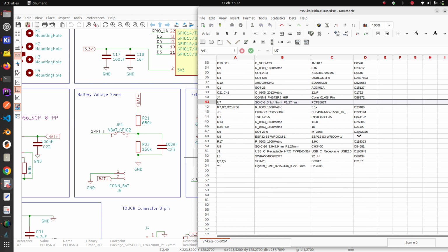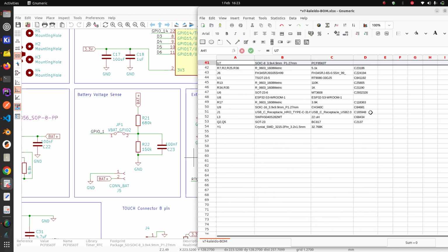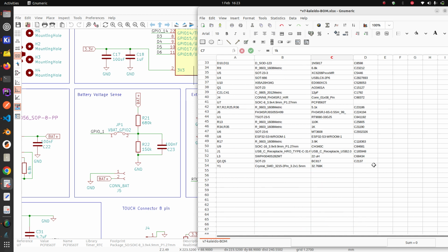However, the rest of the circuit, except the crystal, is there just in case we want to test it. But that's something to take into account. So this pick and place thing that we did from here to the schematics to here, we are not going to leave populated if we want that part not to be soldered by JLCPCB.